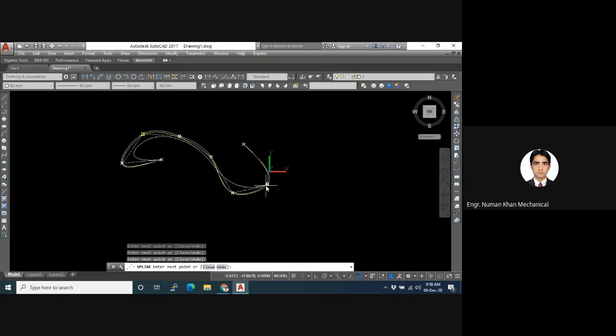With the help of curve fitting, we can draw up to polynomial lines, but with these control vertices, we can draw a very curved line up to 10 degrees. When you click over here, it will have its vertices. With the help of these vertices, this line is adjusted, and it has a higher polynomial degree, not degree of freedom, and we can change this degree as well.